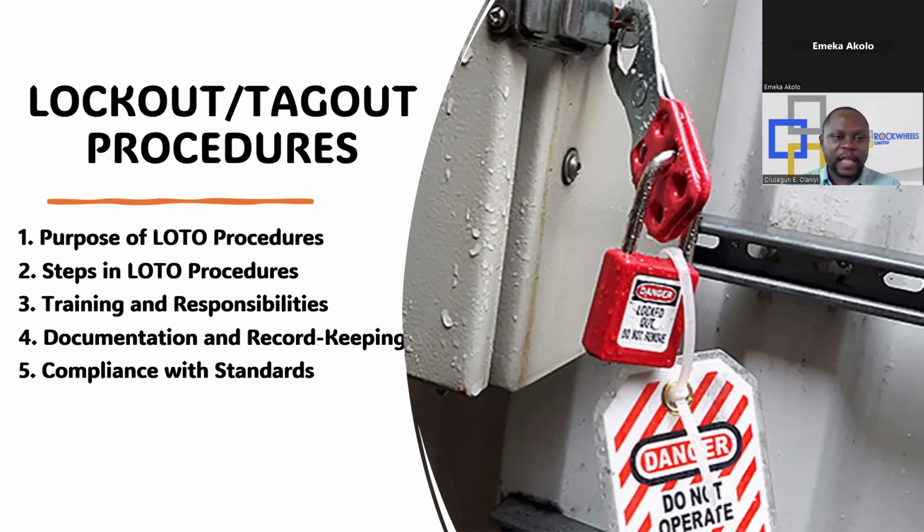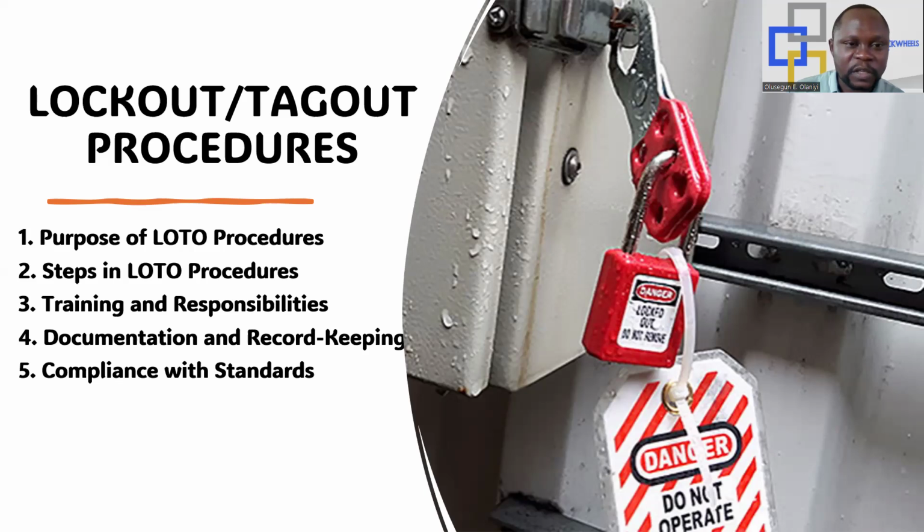If you look, we have different types of lock out, tag out. Now, this particular one that I use, if you look at it very well, you will discover that there are different holes on it. From what I am seeing on this particular one, there are about 4 points where you can lock out, tag out. So when you want to carry out a lock out, tag out on this type of equipment, look for another hole and tag your own. Because this person, when he finishes, will come and remove his own lock out, tag out and go with it. If there are 3 people that want to work on the line, you can see there are about 4.